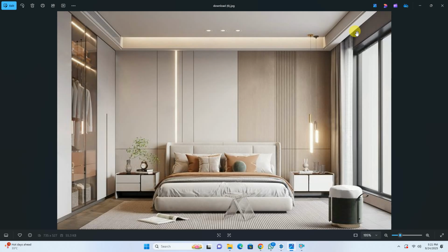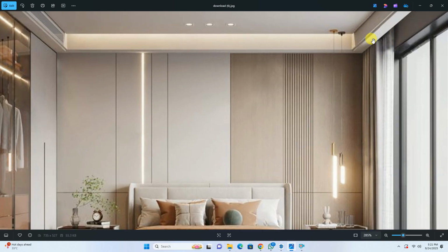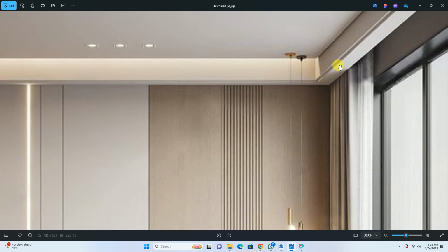Pelmet. We have given it in our last session also. Okay, this gap is the pelmet gap. Okay. So this gap is about 6 inches to 9 inches. It can vary. If we want a double curtain or triple layer curtain, it can vary according to that. If we are using a single rod structure, then we can provide a gap of 6 inches. If we are using two rods, then we should apply a gap of at least 8 inches.